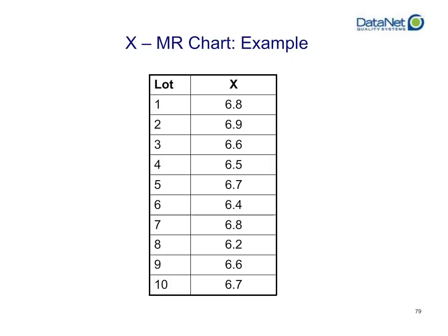You're actually less likely to catch when your process is shifting because you are not plotting an average of a subgroup, but you're going to capture a lot more noise and your control limits are going to reflect this. There's still value to it, and you're going to see it's a whole lot easier to actually do the calculations with an X and MR chart, which is why they tend to get used quite a bit. But generally speaking, you probably want to shy away from this because you can see you just have a whole lot less data relative to how much stuff you've collected, how much stuff you've produced in your actual process.